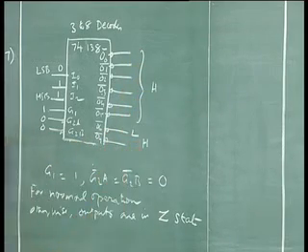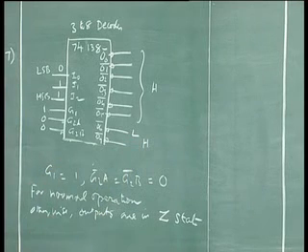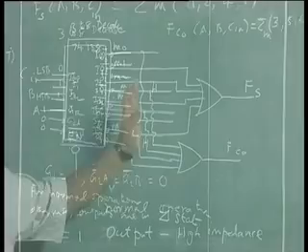Normally it will be the other way. When I say active high outputs, O6 should be high, all others should be low. In this case, this is a practical decoder. It is available: 3 enables, 3 inputs, 8 outputs, active low. So if I want to now use this practical decoder in my adder circuit, can I do that?